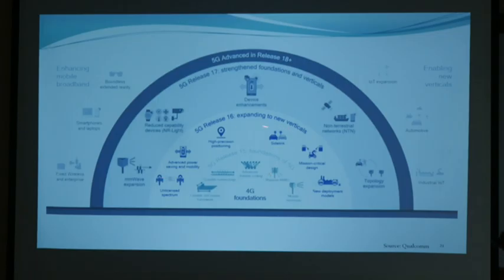So release 16: unlicensed spectrum, as I said, enhanced power saving, mobility, high precision positioning, sidelink, device-to-device communication is introduced in release 16 as well, etc. So in release 17, again the millimeter wave frequency is extended to 71 gigahertz, and reduced capability devices. These are the NR Lite. Your wearable is connected to the base station, device enhancement, and there are two study items introduced in release 17 which are related to non-terrestrial network. Okay, one is the integrated satellite and terrestrial network, and the other one is IoT network with the satellite communication as well. So release 18 is more focused on machine learning stuff.